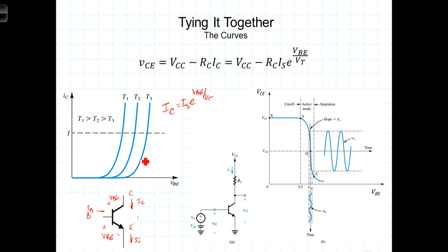And as we saw with diodes, because this is a PN junction, this curve is a function of temperature. T1 being the greatest of these, the greater the temperature, the earlier the diode begins to conduct, or the diode conducts for lower values of VBE.